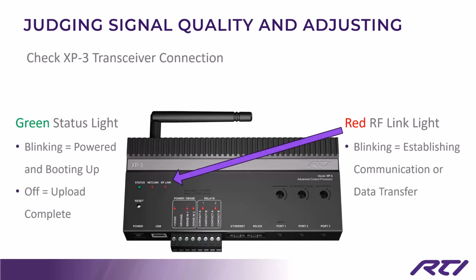It means that it's happening. It's communicating with whatever device. It's looking for that communication. It's established it, but it's also maybe transferring that data. So if it's blinking, it's fine. If for some reason it's not on, or if it's solid, that's when you're going to want to call tech support and say, here's what's going on, and they'll have some additional things that you can try. But just keep those in mind in terms of checking that transceiver connection on both those types of devices.